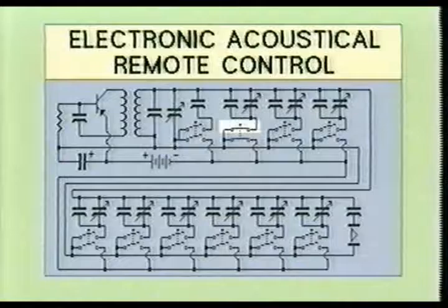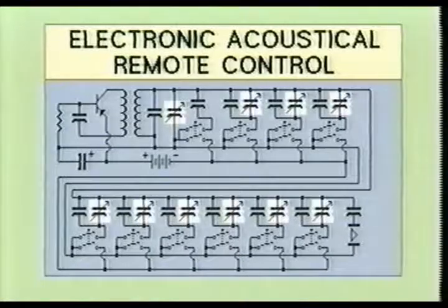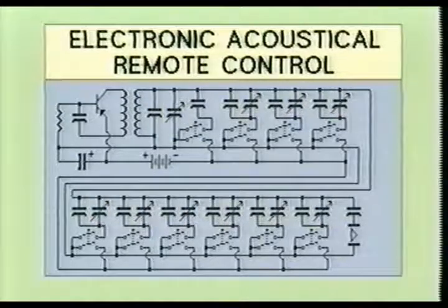When a function button is depressed, which in this case is actually 2 normally open ganged switches, additional capacitance is placed across the secondary tank circuit of this oscillator by the first half of the ganged switch assembly. This additional capacitance will place the oscillator at a predetermined ultrasonic frequency. The trimmer capacitors in each section provide the service technician a means to readjust the remote control device if any frequency would change.